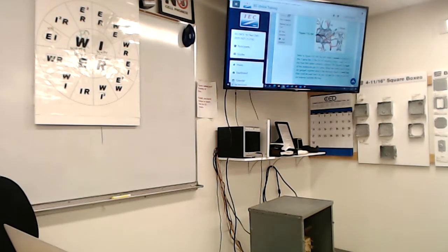Then I have the ground wire. It gets 1 allowance, right? 1 allowance. What else did I miss? Did I get everything? 2 devices, 2 number 10s, 6 number 12s, and 1 ground wire? Is that it?